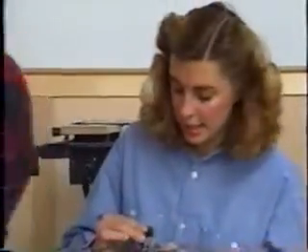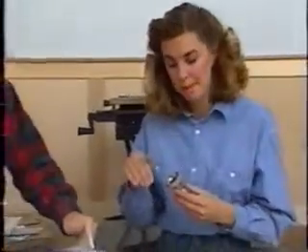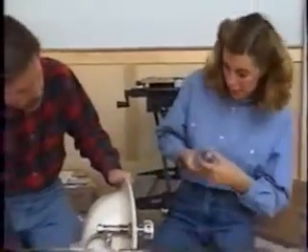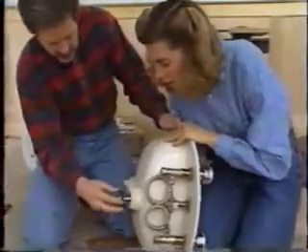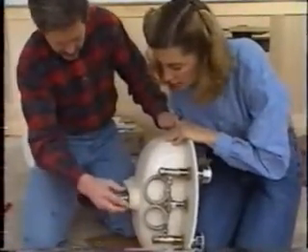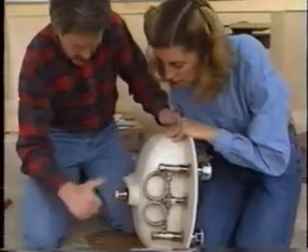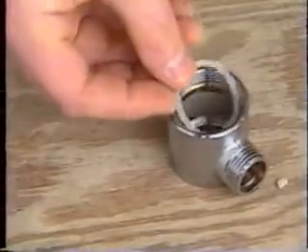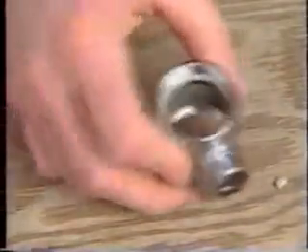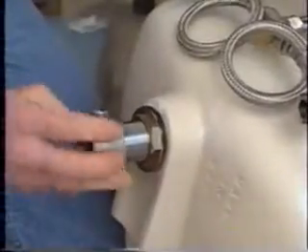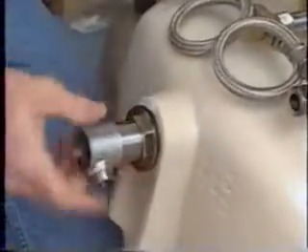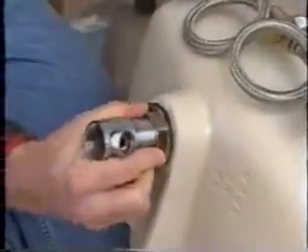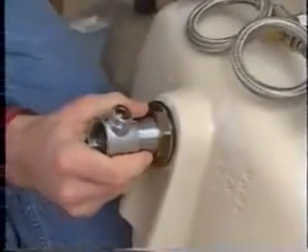The drain connects the sink with the trap and the drain pipe, and we put a ring of plumber's putty around it. Now I can just slip it through the opening. And we use a slip nut and washer to secure the tail piece here to the drain from underneath. We put a gasket in the coupling for our drain stopper and put that on. And once it's secure, we'll line it with the back of the sink. And we'll tighten our slip nut in just a second. There we go.